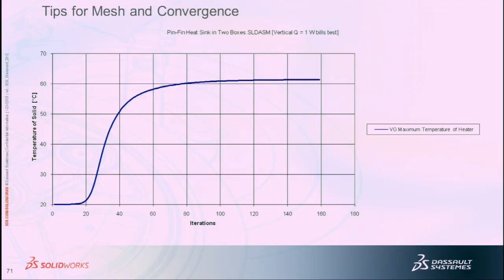So yeah, the problem wind tunnel people have is the velocity goes to 0 at the walls, whereas in our case, we don't go to 0. It's a pressure condition. You can move the ground at 400 miles an hour in the air, or they can't do that. Right. But let the software tell you. Just throw it out there and look at it and say, oh yeah, I see, there's something going on here. A lot of times that's where the adaptive comes in. Turn it on with a coarse mesh, turn on the adaptive, and it'll tell you where the areas of interest are.